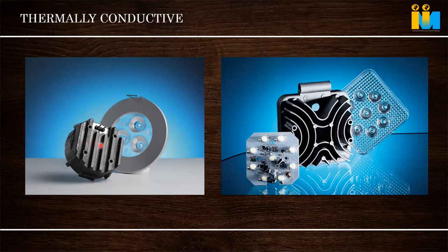Then how do we change that, how do we do the design? In this case, we increase the area of air contact by doing this pin design. If aluminum has 4 pins, here we have to do a thermal FEA analysis to see that and design this type of product properly. Here we get better productivity and mass production. All these things will be easy in this case, with lower weight of the part. For this reason we are shifting to plastic for small parts. But this pin design and thermal analysis has to be done.